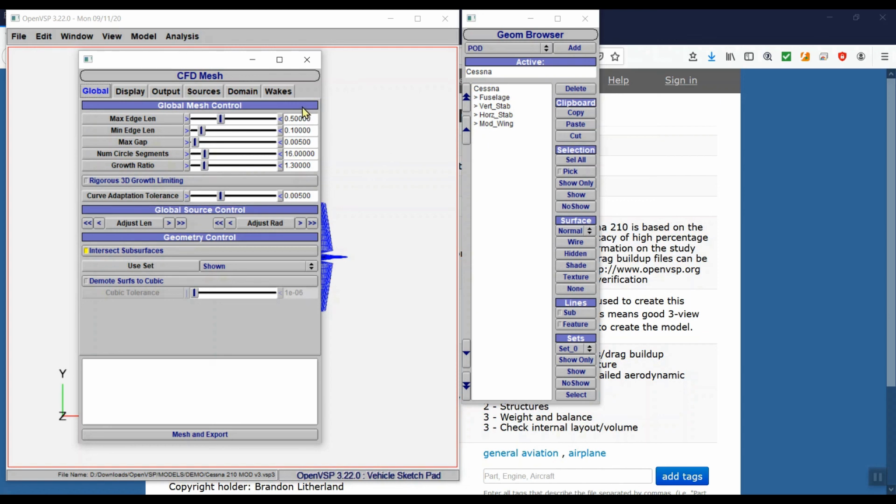So one of the things that we want to do is try to generate a mesh density of less than 15,000 triangles. And that's because more than 15,000 triangles, when you go to analyze it in Flow 5, is not going to add a lot in the precision of the analysis, and also it's going to use up a lot of memory in your computer, and the process will be quite slow. Typically we're looking at a triangle mesh density between 5,000 and 15,000 triangles.